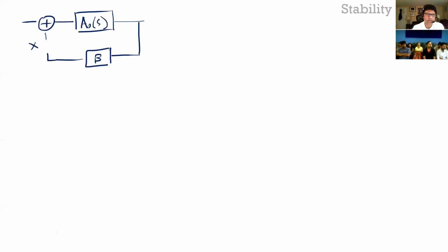Let's say we'll break the loop here, and we'll provide some V in here, and we'll monitor the V out here, and this node is equal to 0. Whatever load is here, we'll obviously connect that load, but we'll inject an input here, and we'll see the output here with all the loadings and everything, DC bias conditions met. And as we start doing amplifier design, we'll use this technique of breaking the loop with the loads to analyze this.